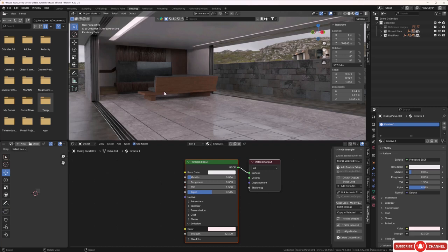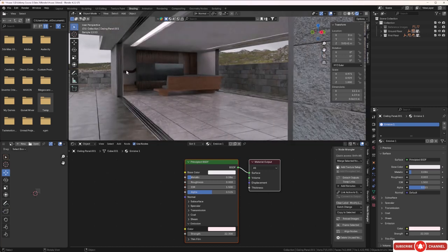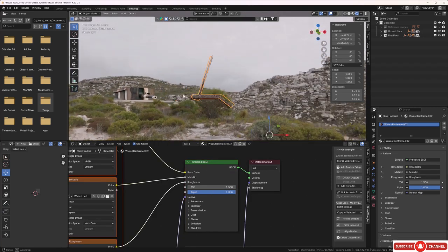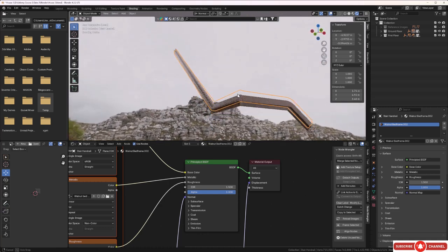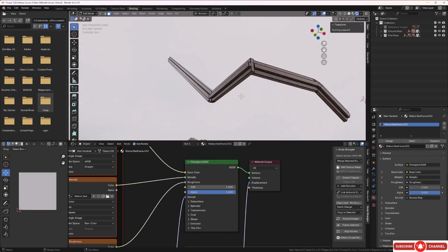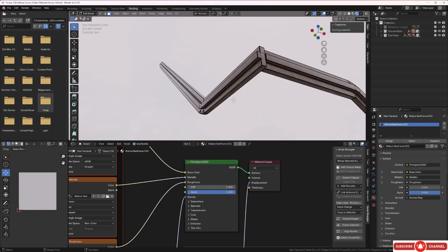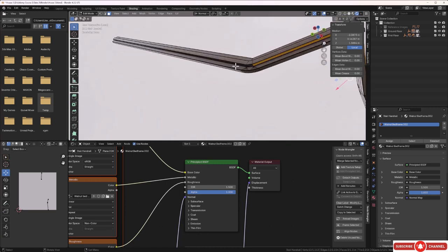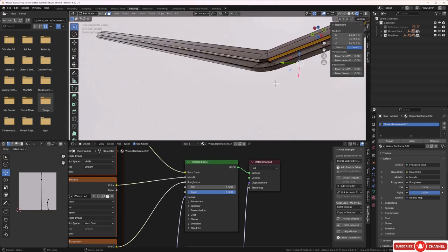So I want to apply one more light, and I'm going to apply it to the underside of our stairway handrail. I think that'll be quite effective. So let's go ahead and do that next. Let's maybe just grab this handrail on its own, and let's hit the / key to isolate it. And let's go ahead and tap into edit mode, holding onto it. So I'll hit the tab key. Make sure you've got face selection on, and then select maybe this face here. Hold shift and select this one, and maybe this one, and one last one, which will be this one.